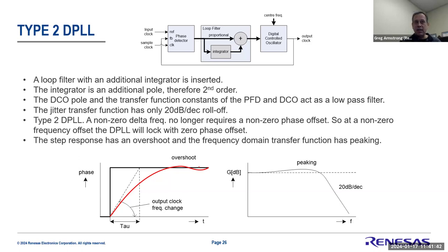Because that represents the error of the local clock to your high stability frequency clock coming in, over time the integrator is going to represent that over a long-term average. So your proportional term starts stabilizing, hopefully getting closer to 0. And that's where it's going to settle, a 0 offset to the input.